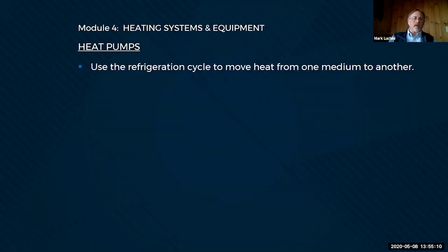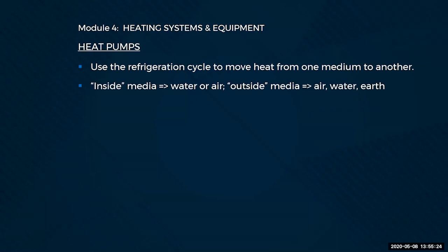So, heat pumps. We're not burning fuel with heat pumps, right? We're just using electricity. We use a refrigeration cycle just like we did for cooling. We use the refrigeration cycle to heat. So, your inside heated medium can be either water or air. Outside, it could be water, air, could be the ground, right?